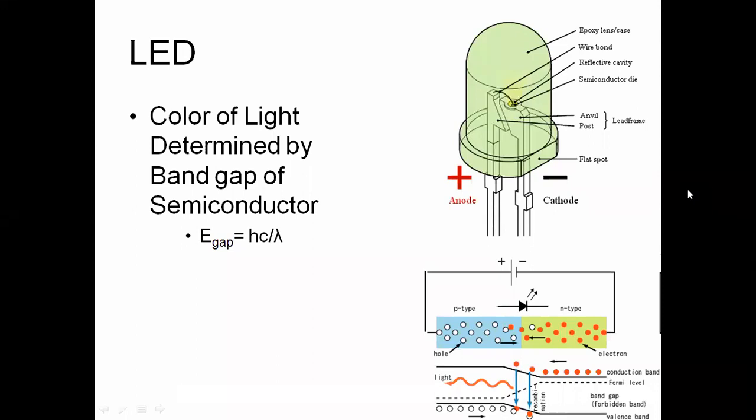If you keep this LED at room temperature without giving any external source or external supply, even then it has a depletion layer, isn't it? This depletion layer we can call a potential barrier. What does this potential barrier do? It doesn't allow the holes from the p-type to enter into the n-type, and the electrons in the n-type will not flow into the p-type junction because of this barrier, isn't it? That barrier we call a potential barrier. It acts as a partition between the p-type and the n-type, isn't it?